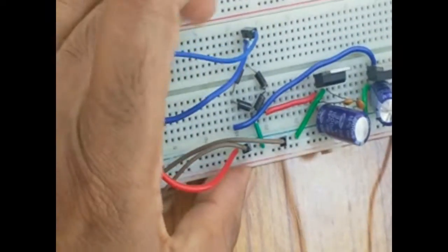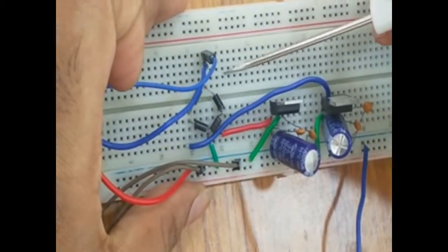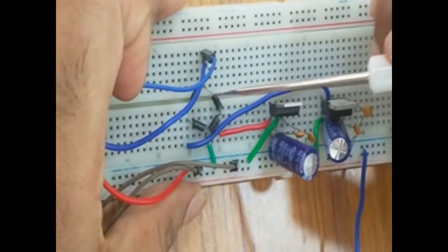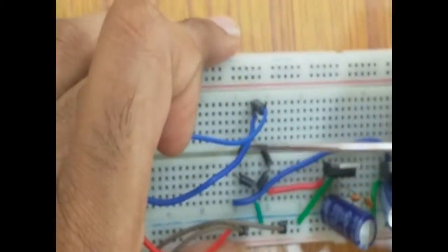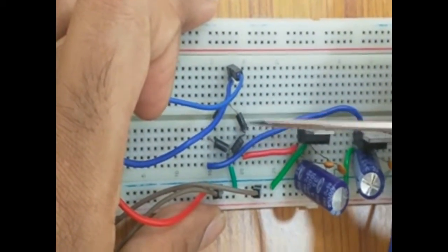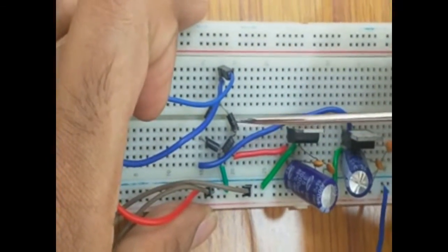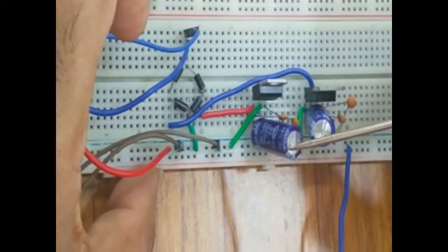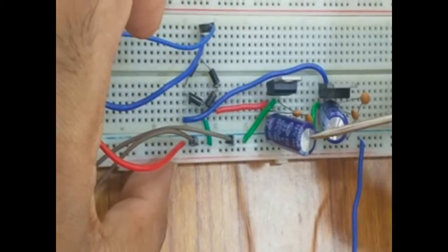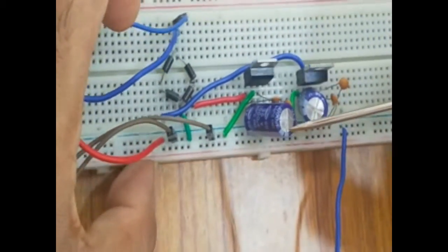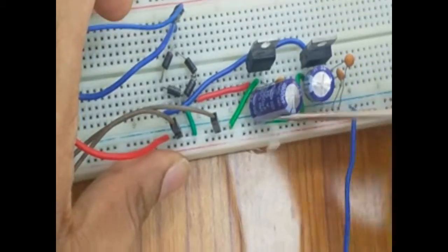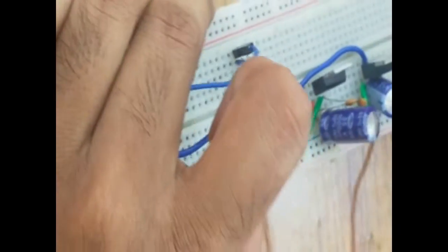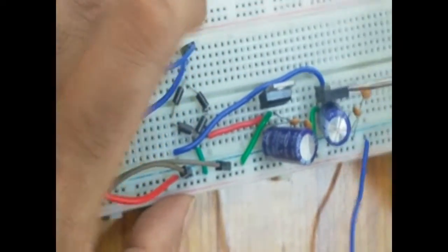In this plus minus DC adapter, the first stage is the bridge rectifier. Here we have four diodes: diode 1, diode 2, diode 3 and diode 4, formed in a bridge shape. This is a bridge rectifier. After that, in series with the bridge circuit, we have a filter circuit as the second stage. I have connected two filters. One filter is for the 7805, which is 1000 microfarad, and another capacitor is given to the 7905.